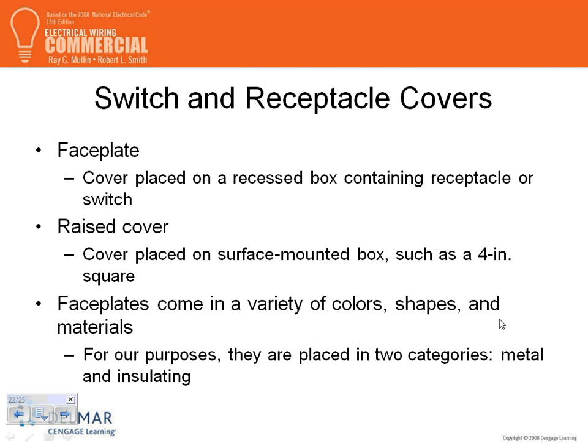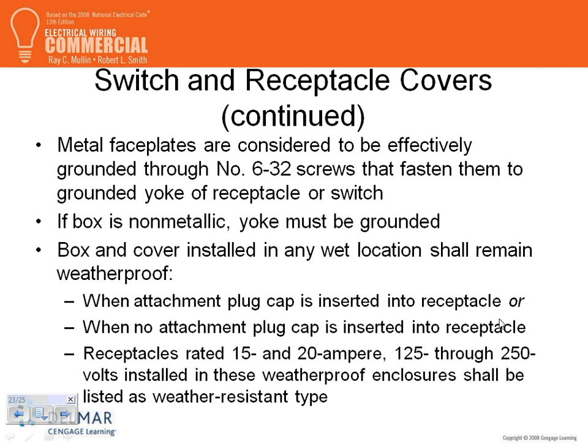Okay. All right, so this just talks about the plates, face plates. If it's a raised cover placed on surface mounted boxes, such as 4 inches, you have to attach the device to the cover with two screws by code. If it's metal, you have to ground it. It's grounded by being attached to the yoke and the box. If it's non-metallic, who cares about it?